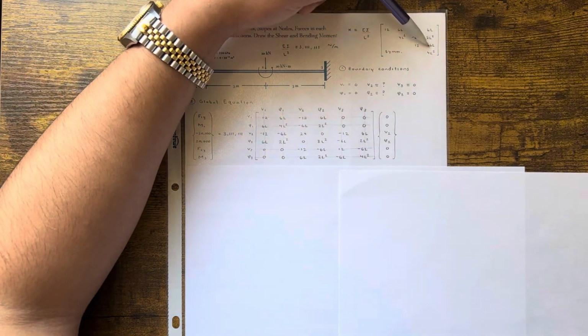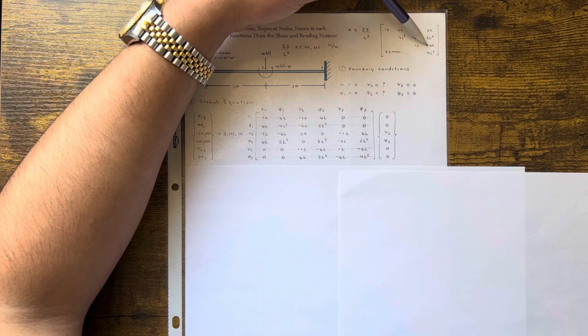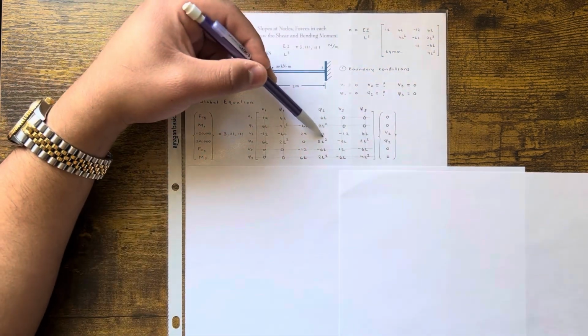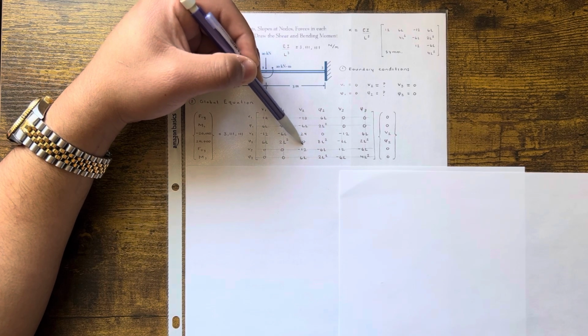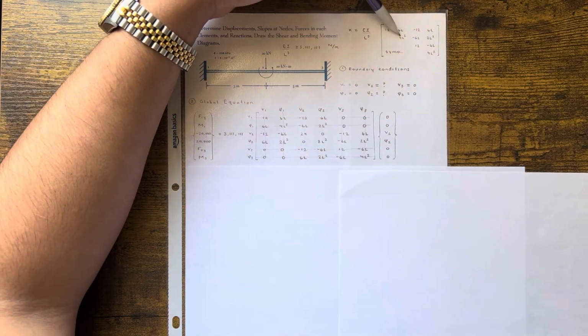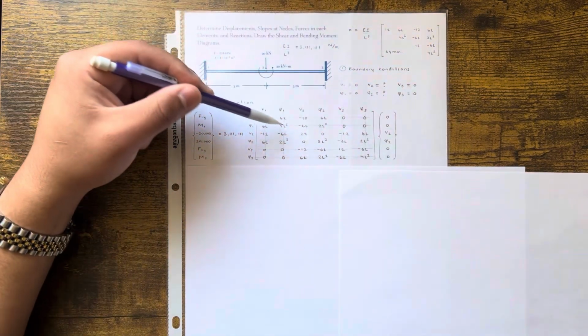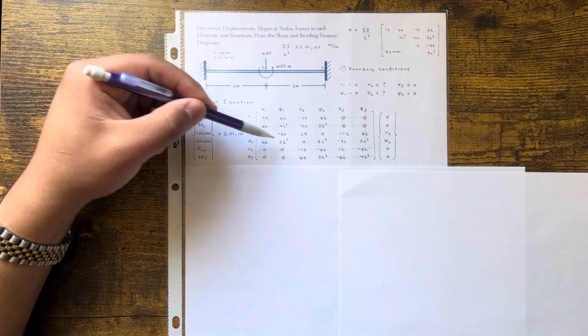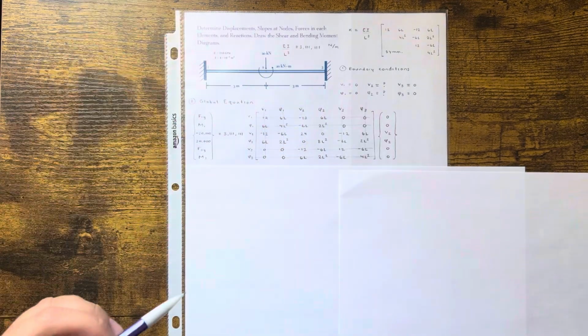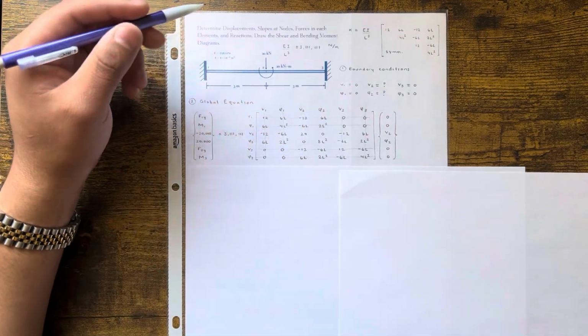On the next one, right next to it, you have a negative 6L here, and the 6L here is going to give you a 0. And it's symmetrical, so this one's also 0. Same thing, this 4L squared is going to get added with this 4L squared. Now just go ahead and plug them in. Do each one separately, and you'll see that these 4 you have to add, because they're in the same spot, since they both share node 2.